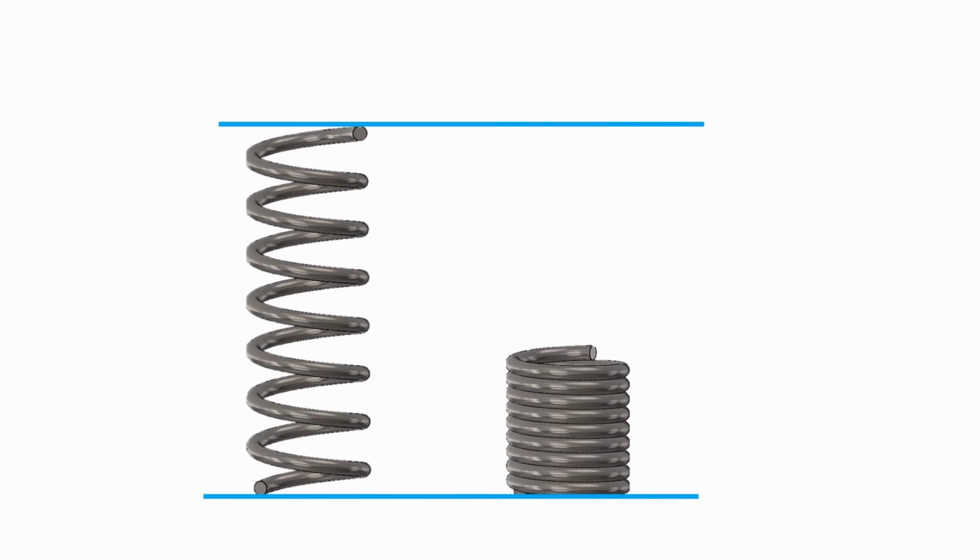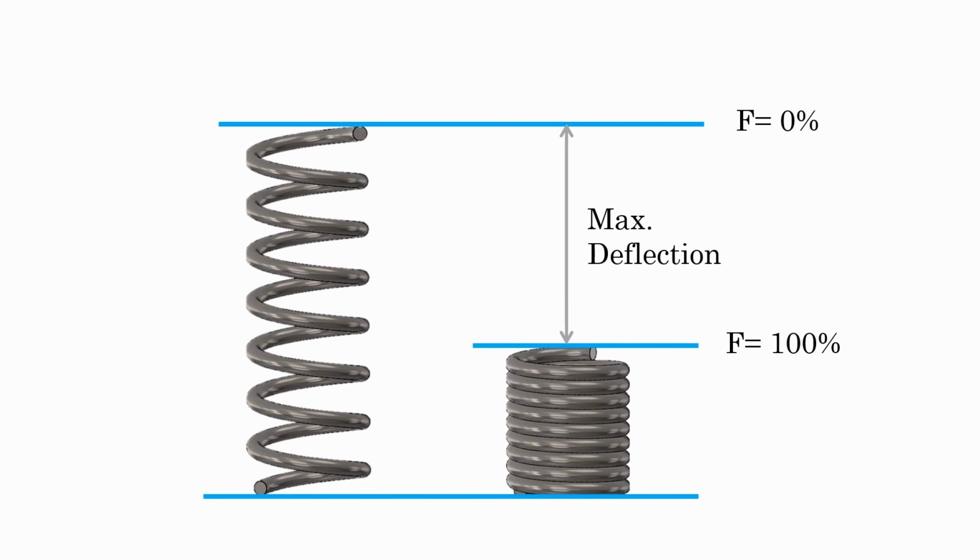Now, if you say, why not just use the mechanical compression spring? Why the gas spring? So here the biggest disadvantage of a mechanical spring is the force variation with compression. As a mechanical spring compresses, its reaction force increases and reaches its full capacity when it's fully compressed. So at the starting of the drawing process, it might not provide enough force, which can lead to the wrinkles defect.